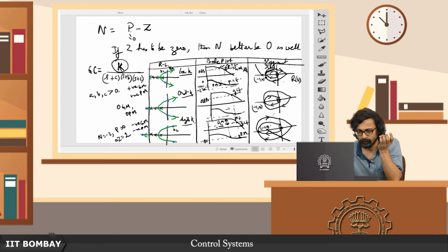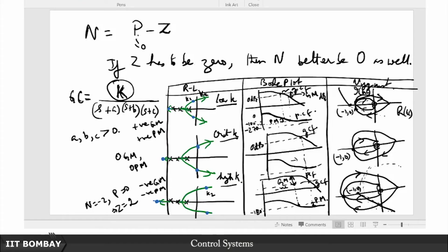If you try to find its crossing and take the angle at that crossing, remember this is the segment that we drew earlier. This segment obviously had multiple crossings, but the one crossing that matters has already ended up here. So if you have to have a phase margin, you better reduce this phase, you have to bring it down. So you have basically a negative phase margin here.